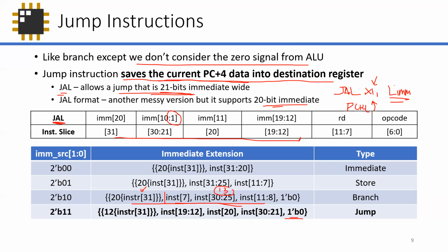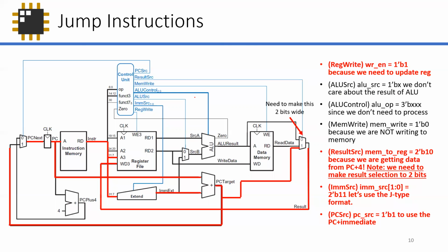But maybe we'll add a little bit of details about jumping. Oh no, actually, I did spoil it here. Aha, something's not right in my drawing. So let's go through the steps again. You have the jump instructions. Again, we go to the program counter, decode the jump instruction, and specify the address that we want to write into. But this time, the reg enable is asserted. Why? Because we're going to write into a specific address.